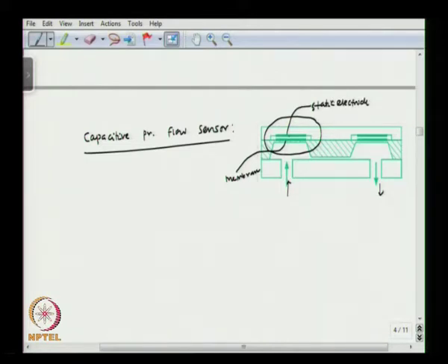And as the flow rate changes, so does the pressure drop. So, since the pressure drop is modified, the pressure inside this chamber is changing, and when the pressure changes, this movable membrane moves with respect to the static electrode. So, there is a change in the capacitance that happens, okay, and that change in the capacitance is related to the flow rate.